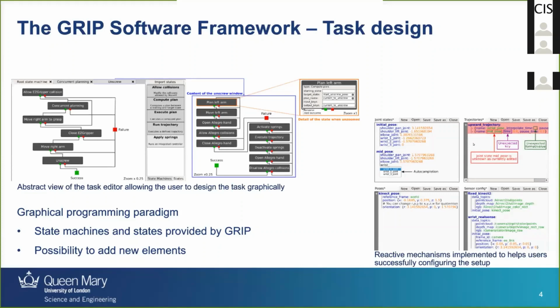Instead of generating the trajectory message manually, which can be a bit painful, you can define joint states in another editor and use these joint states to create a trajectory by saying, oh, I want my robot to go from this joint state to this one and this one, given a certain amount of time, so interpolation time and pause for each step.